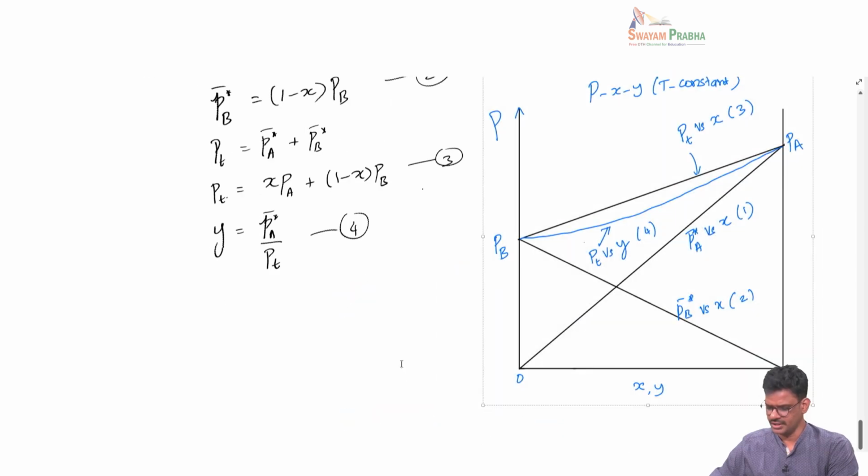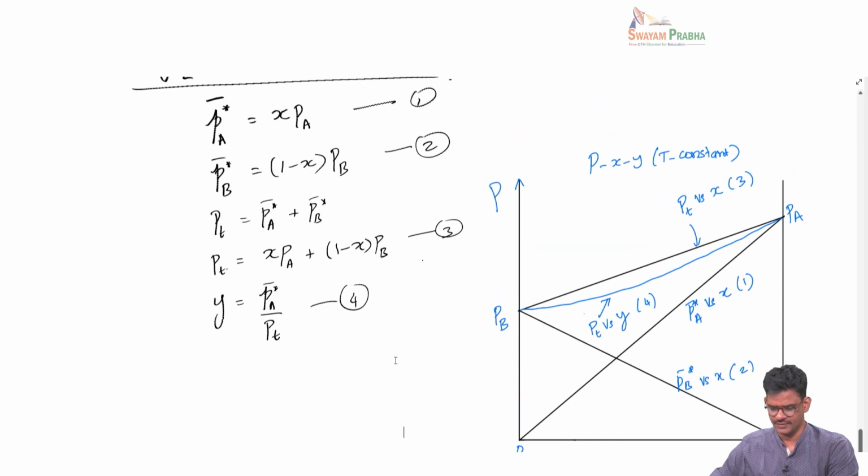So here you can see the consequence of this. Let's say I am plotting Pxy, and I assume temperature is constant. Why am I saying Pxy? Because Raoult's law relates the partial pressure and total pressure, so it's better to look at how Pxy are related for a constant temperature. The temperature enters these equations only through the vapor pressure data, because PA, PB are functions of temperature. If you change the temperature, PA, PB will change. So here let's say the temperature is held constant.